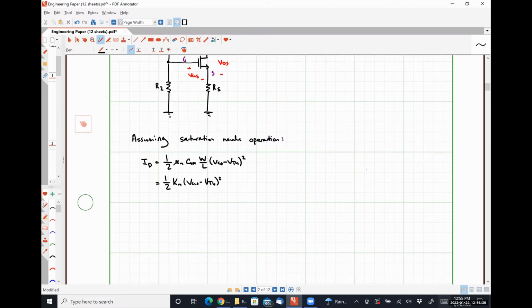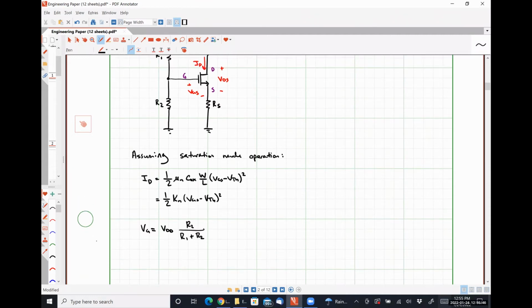And so that tells us that VG is equal to VDD times R2 over R1 plus R2. Everybody okay with that?